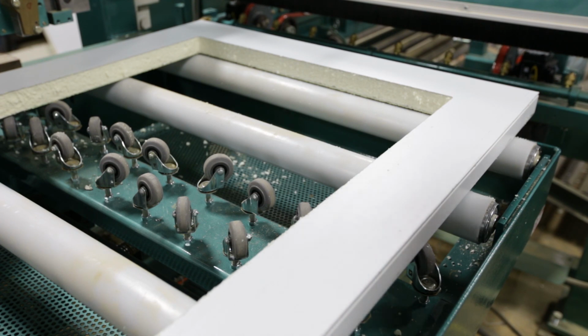If you check your program and those are all entered correctly, go back to the parameters that you've entered on the DL-NCD software and make sure that all those are entered correctly. If you enter a door width that may be off, your cut's not going to be centered because it's trying to cut to a width of the door that's not matching up with the width that you've entered. If you've checked both of those and those seem to be on, the third step is to go back and make sure that the calibration of the machine is correct.